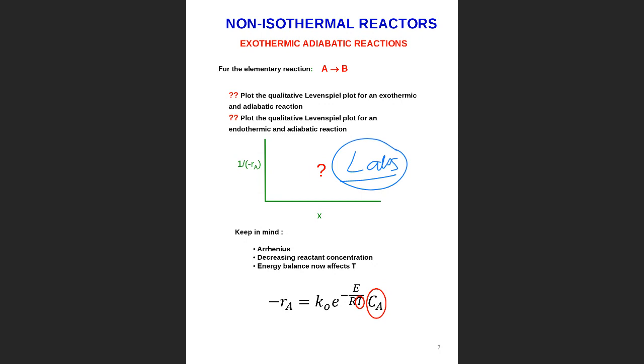I want you, for either TUT 2.1 or TUT 2.2 with the right detail given, to construct a Levenspiel plot. You can decide at which point you feel you're up for it. The paradigm that you need to get rid of is that the Levenspiel plot is associated with a specific reactor type. It is not. It is a function of what my initial concentration is, where I start, and therefore how fast I can start. And it is a function of your rate expression.